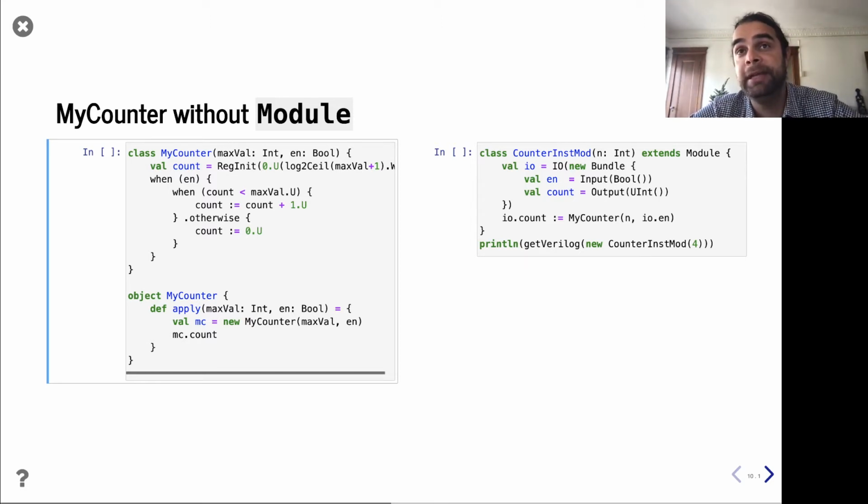Nothing's wrong with it, but we're thinking about how the design turns out. Remember, modules have very strict rules, I need to have I/O, and modules will appear in the FIRRTL and the Verilog. Now, in a good hardware design flow, your CAD tools will optimize across module boundaries. However, at various stages of human reasoning about the results, as well as debugging and just talking about things, modules still represent an important level of abstraction and encapsulation.